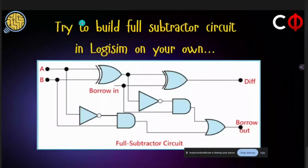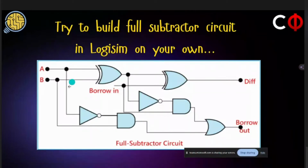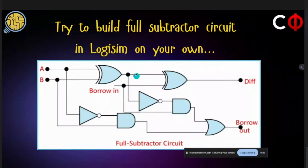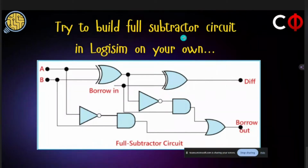And you can try to build a full subtractor circuit in Logisim on your own. This is the final circuit that I've given to you as reference. You can try to build it on your own and just check it out. It's very easy. Again, you can see this is nothing but a half subtractor. This is another half subtractor. This XOR gate, NOT gate, and AND gate put together. And when you put two half subtractor circuits with an OR gate, you get a full subtractor.